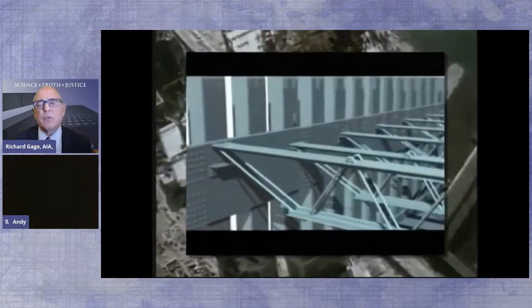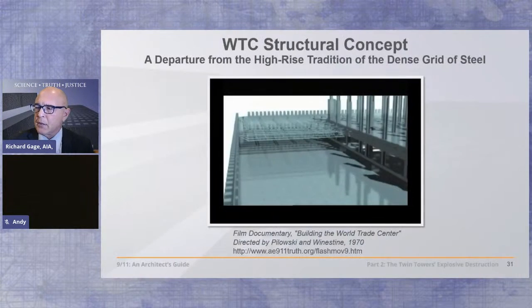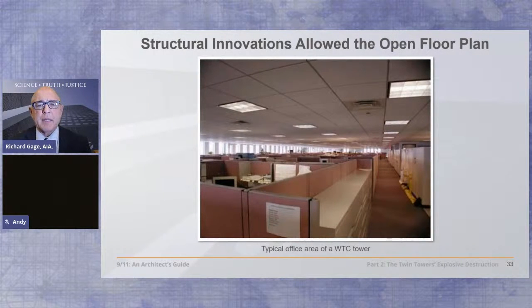And in between these 2 structures were laid these floor panels supported by these T-bar joists, thin steel joists with 4-inch thick and then 8-inch thick concrete on the mechanical floors. So this tied the structure together, but that allowed incredible open office planning, 60 feet on one side, 35 feet on the other side. So you see something that has never been seen in skyscraper construction for the previous 100 years, openness.